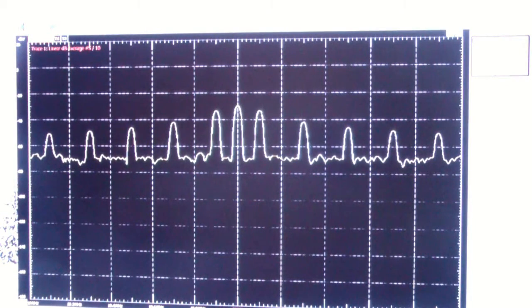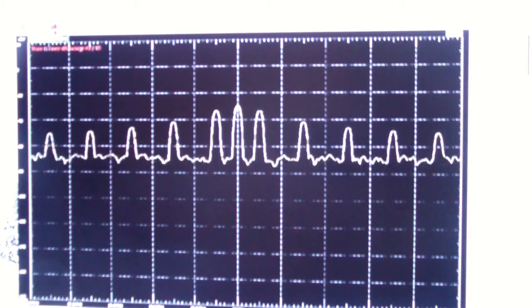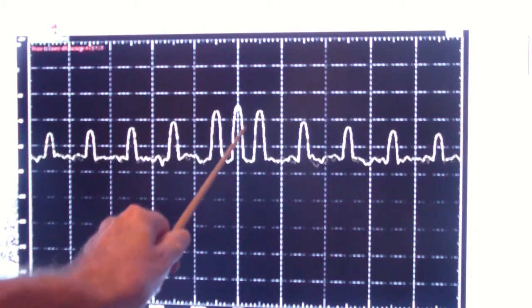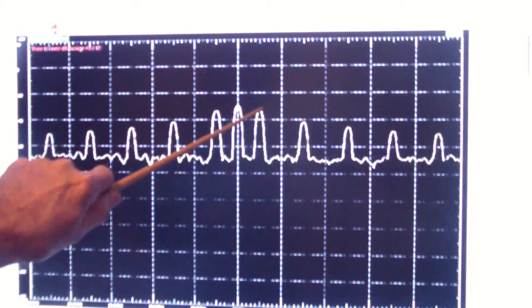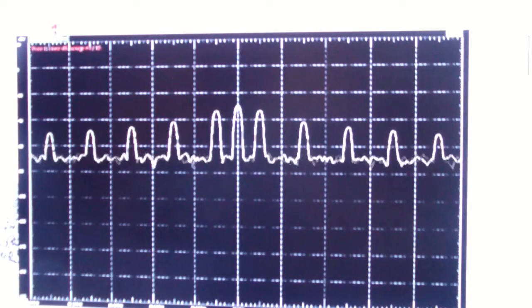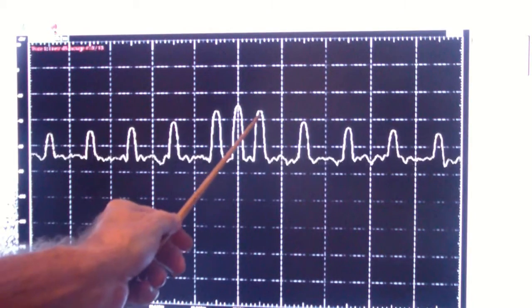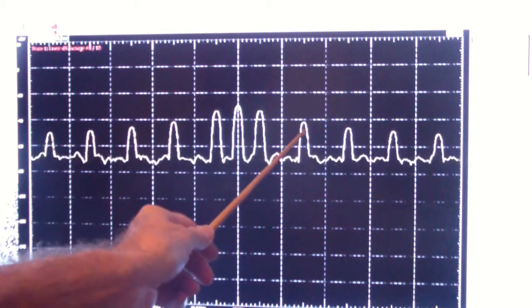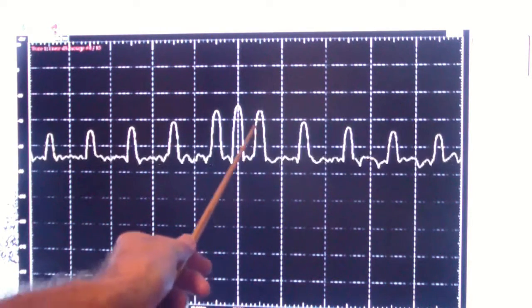And here is the spectrum analyzer. I'm going to now run it to show you what the spectrum of the signal looks like, so that you can get an idea. This is the carrier in the center here. To the right and left are the first sidebands, that is the first upper sideband and the second upper sideband. And by that, this is the entire sideband because we're looking at a square wave. So this is, for example, the fundamental frequency. This is the third harmonic, fifth harmonic, and so on of the modulating signal.